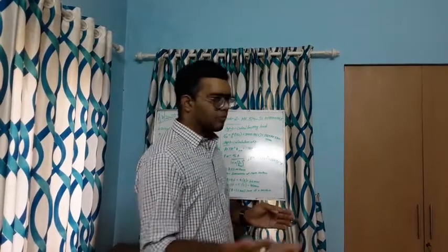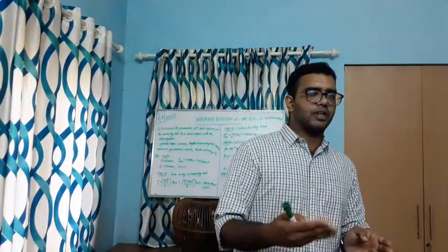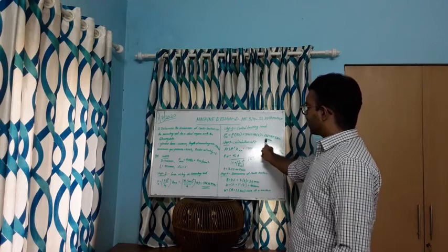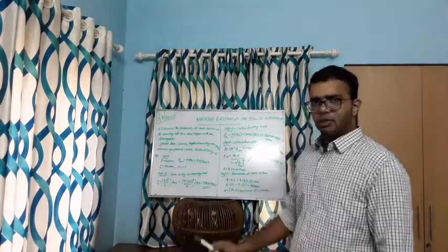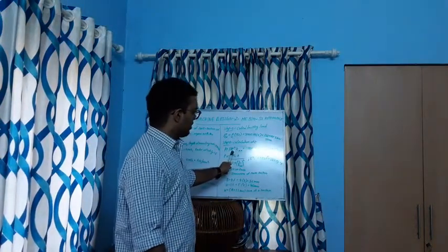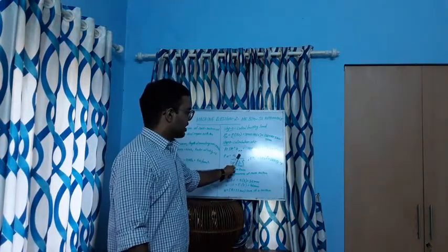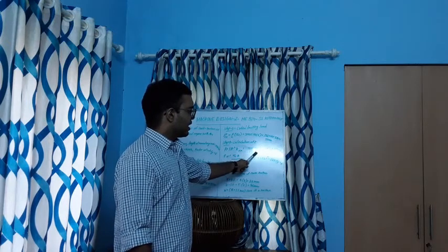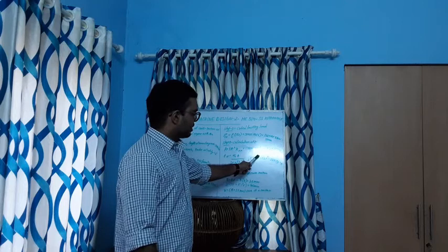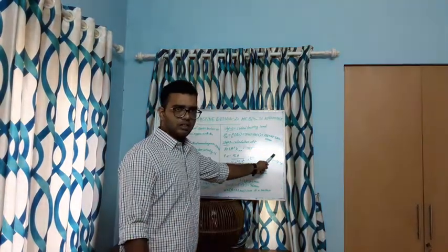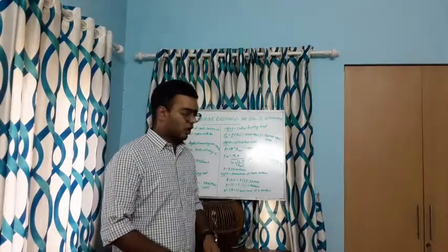The third step, which we get from the data book, is to calculate the value of small t, from the value equivalent to the critical buckling load. It's in the data book. A is the area, and A is equal to 11 t square. Kxx, the radius of gyration, is equal to 1.78 t. The constant a is equal to 1 by 7500, and sigma C, the stress, is equal to 330 Newton per mm square.